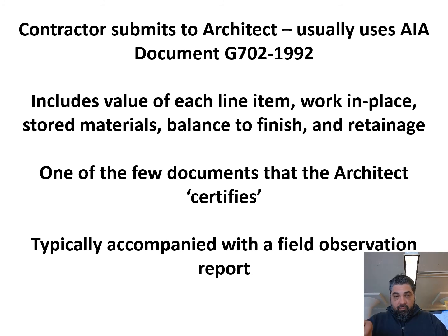The next column will be stored materials. And so those are stored materials on site. Now, it's possible that the contractor may want to store materials off-site. The problem with that is that it's not covered by any of the contractor's insurance, and it's not covered by any of the owner's insurance. So all of a sudden, the subcontractor could buy something, bill for it, the owner would pay for it, but it never showed up on site.